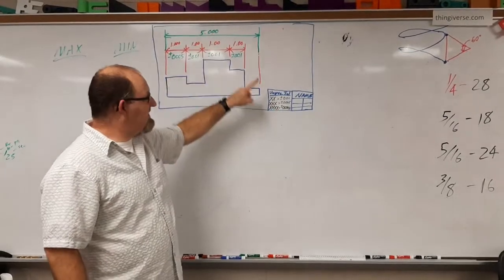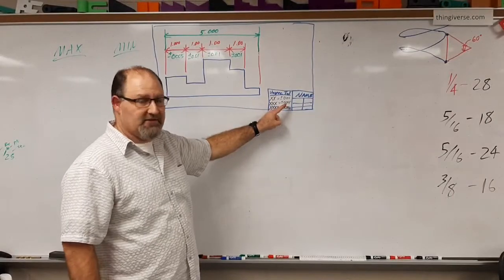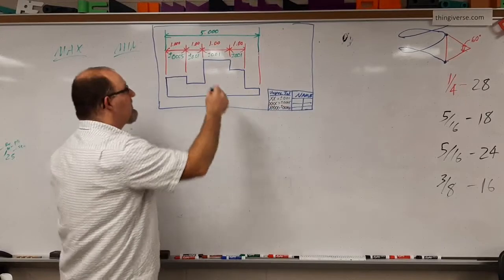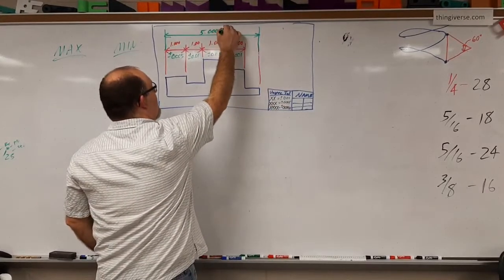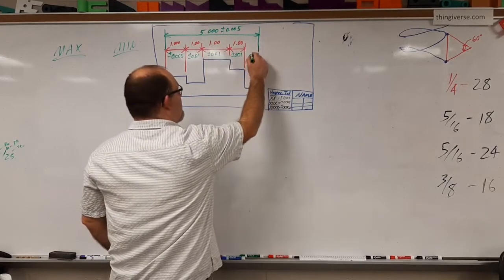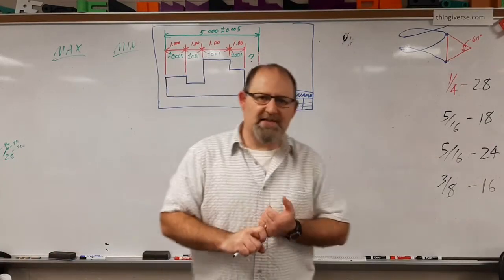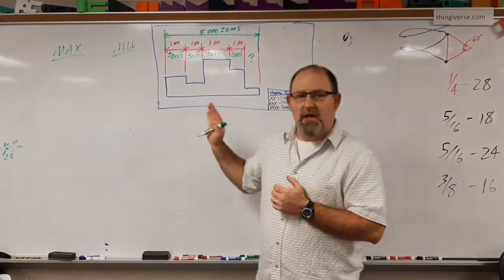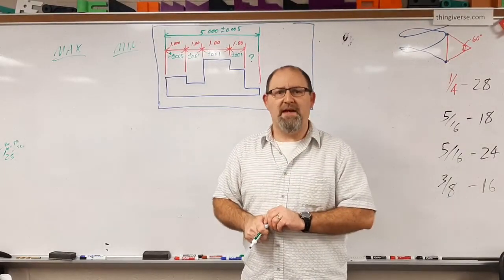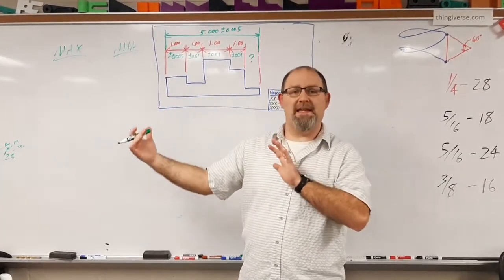Because it's 3-place decimals, that means this is plus or minus 5/1000 of an inch. So in this particular case, we still have these first four the same. We have this overall dimension here, and I'll put on there plus or minus 5/1000 so you can see it. And then we have to ask ourselves, well, what is this? Okay? So a couple of things here. In the previous one, when we looked at just the chain dimension, we saw the maximum could be 5.040, the minimum could be 4.960. So 40 thousandths above, 40 thousandths below, that's the overall length of the part.